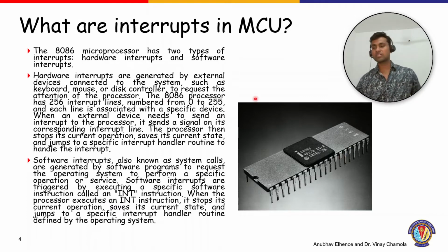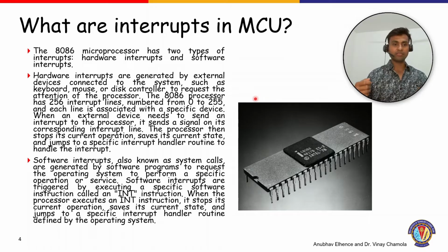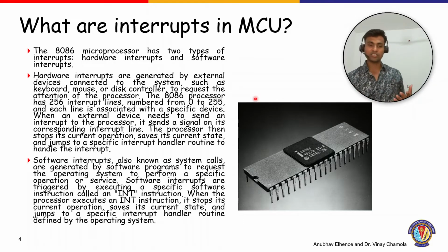So hardware interrupts are externally applied interrupts, and they put a high signal onto one of the particular pins, and then to tell which interrupt is being raised, they apply a certain address to the interrupt lines. More on this in later sessions.